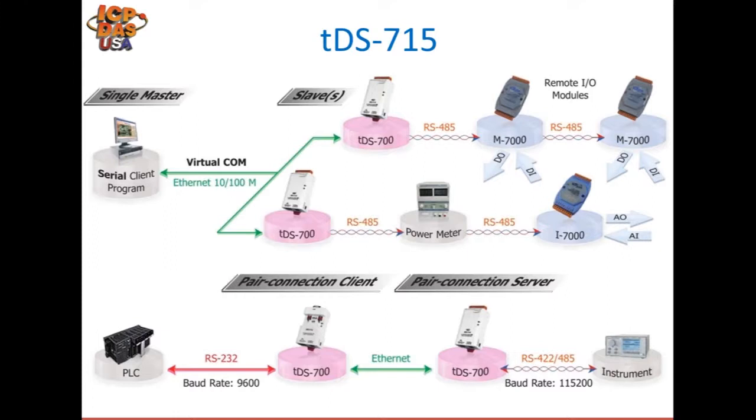DCON protocol. And the bottom picture shows a PLC connected by RS-232 to a TDS-700, and it's configured in pair connection so that anything that comes in through the RS-232 connection from the PLC goes through to the instrument at 115200 baud rate to the instrument.